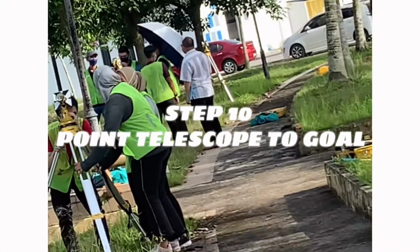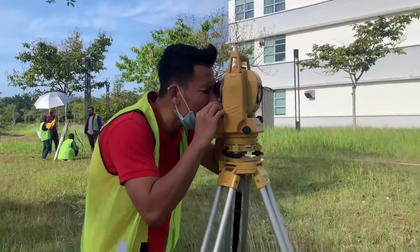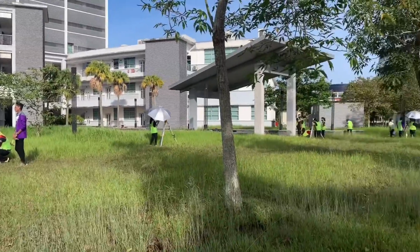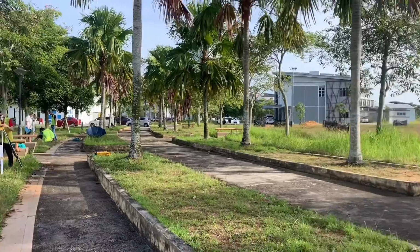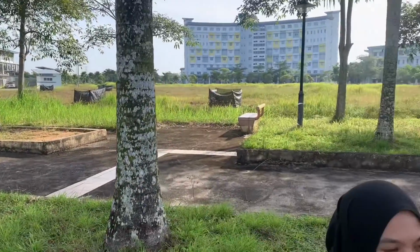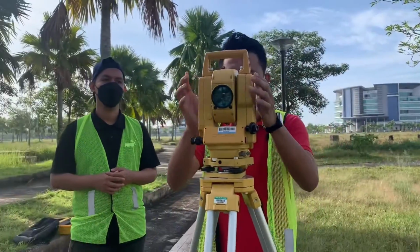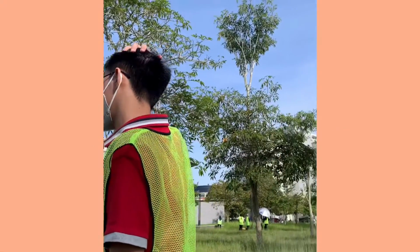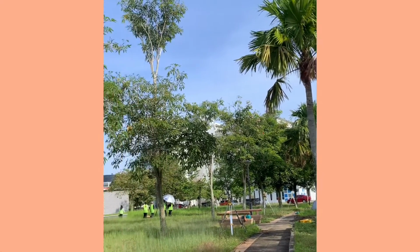Step 10. Point telescope to target. Release the horizontal and vertical clamps and point the telescope to a featureless bright background. Adjust the reticle focus adjustment until the reticle image is sharply focused. Point the telescope to the target and adjust the focus ring until the target is focused. Step 11. Repeat the procedure. Repeat the procedure at the prism setup and stations 1 and 3.